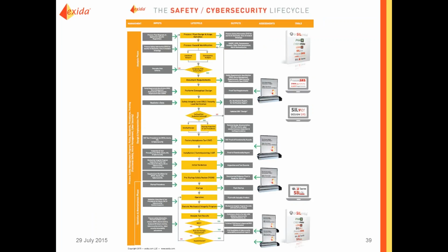And there's kind of 5 places that the standard talks about the assessments being performed. 1 would be after conceptual design. 2 is after detailed design, typically right after the FAT. The required one that must always be done is prior to startup, and then you can have one after modifications or one before commissioning or decommissioning. So that's a proposed maybe 6 gates to try to improve the overall design and actually achieving the required risk reductions.